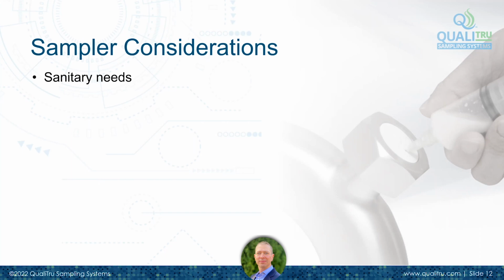That's probably like a sanitary valve in my process where the stem travels through an O-ring and gets a similar squeegee effect. I would say yes, except for in this case, the septum can be used 7 or 12 different times with different squeegee effects. So everyone is brand new. With your sampling valves, there's going to be a back and forth on the same O-ring, and it tends to invite in environmental contamination over time. That's why their O-rings will end up failing and you'll get contamination.